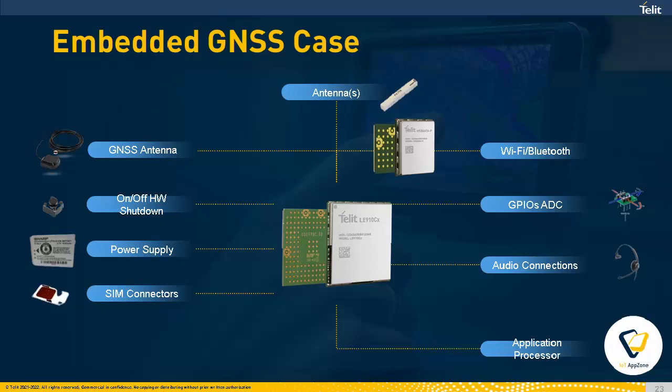In case an active antenna is not applicable for the customer use case, a passive antenna with a pre-filter stage and an LNA can also be taken into account.